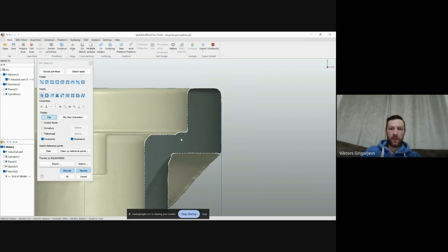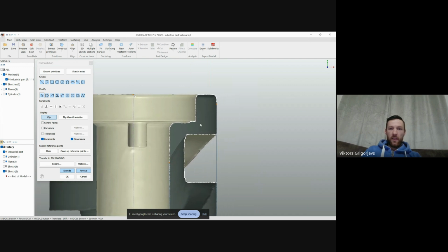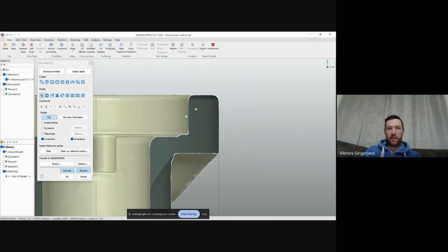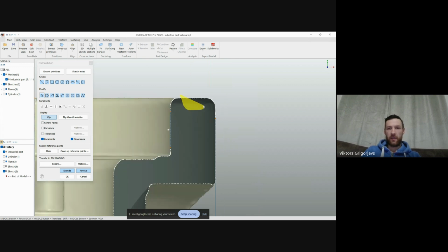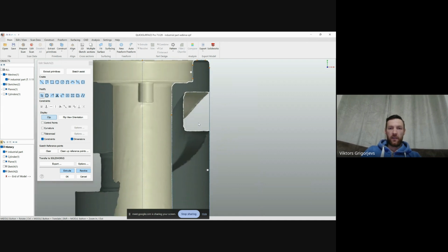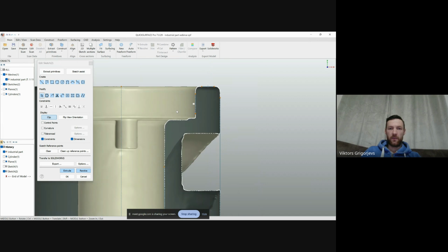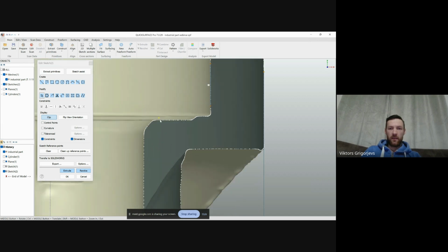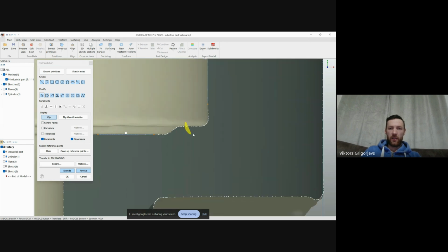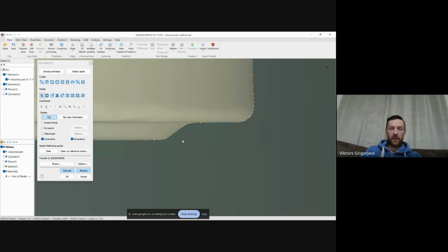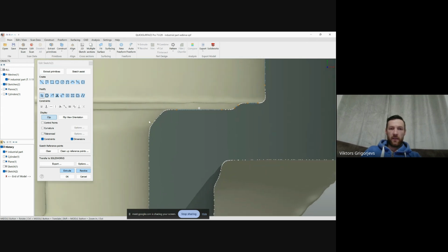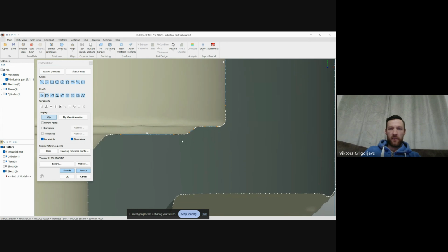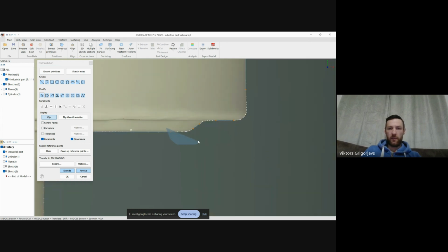But if someone is not familiar yet with this, you can hold your Shift button and drag over these points, and the software automatically fits lines or arcs. It depends what kind of shape is sliced. Later, if you're holding Control and hover over two ends of lines, it will just connect them.